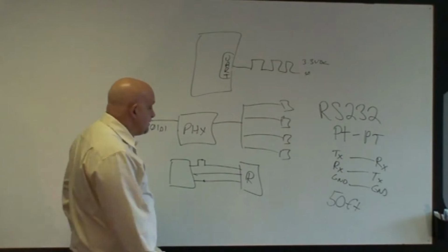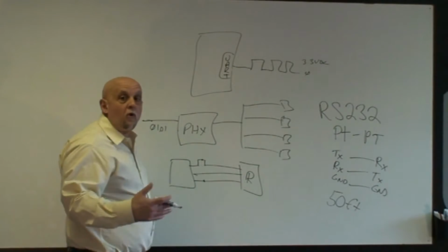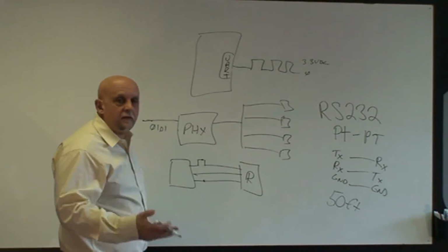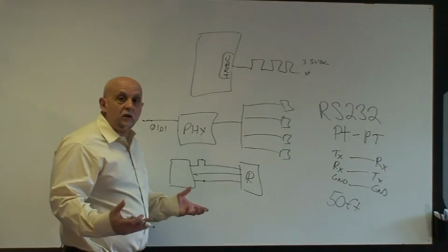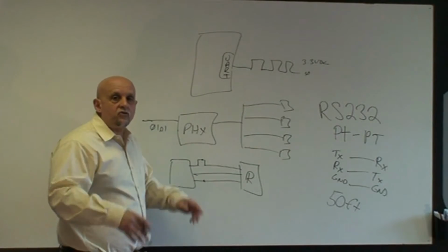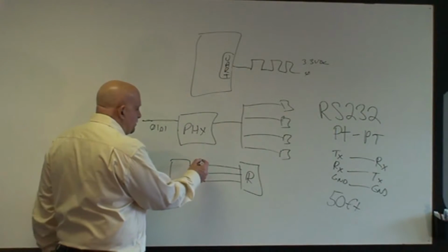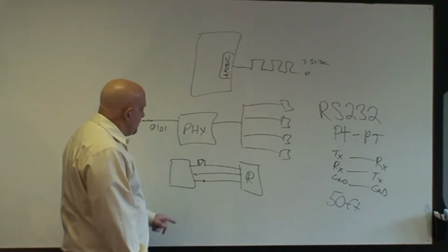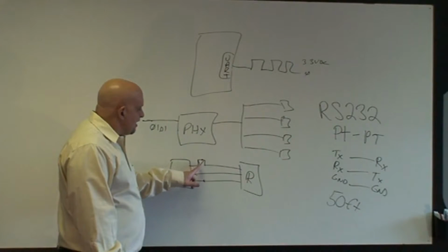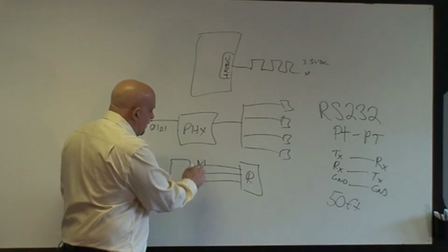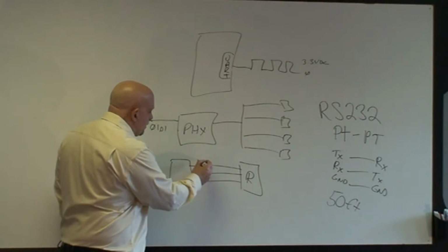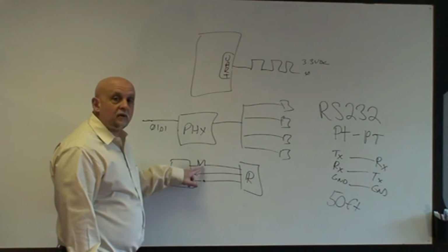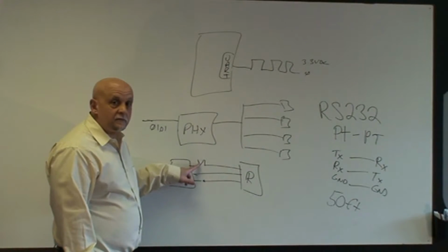If there's a little bit of noise in this system, maybe there's a motor nearby. In an industrial environment, we're going to have noise because we've got lots of things going on and off. Every time you turn something on and off, there's some kind of electromagnetics. Those things get picked up by these wires, and that could force the signal down. So now it's kind of iffy. That thing that we thought was a 1 is now in reference to this as well. Is that going to be picked up as a 1 or not?